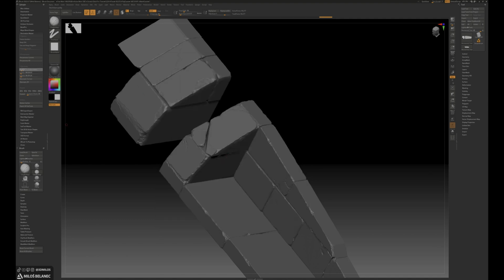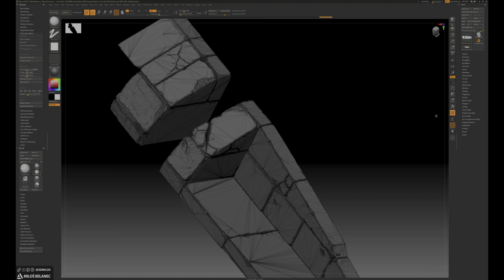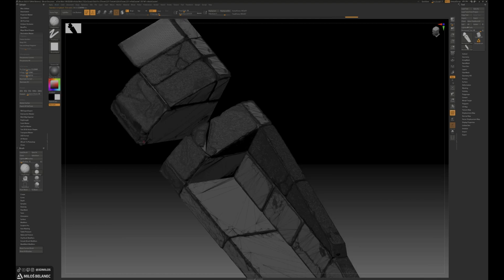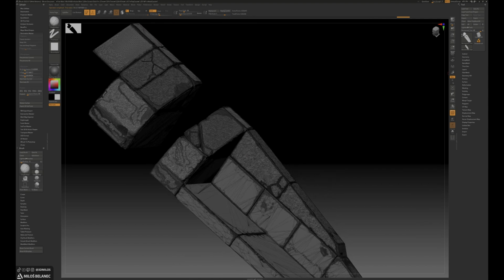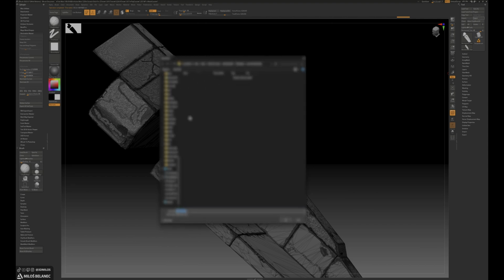The first one will be low poly and the second one will be high poly. Basically the shape of the model must be the same, but the difference is in the poly count. Low poly is with a lower poly count, and high poly is with better details with a higher poly count. This workflow is the standard for the game industry, and we use it in trailers and in cutscenes. Of course, when we have some big and heavy models, we can bake it.